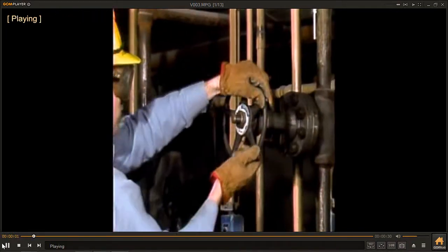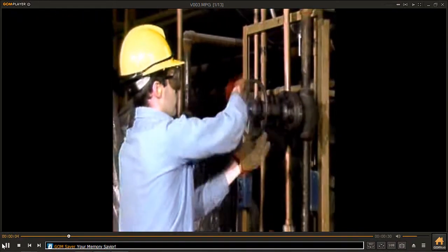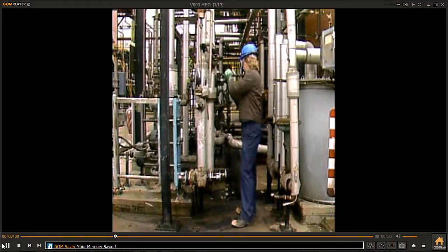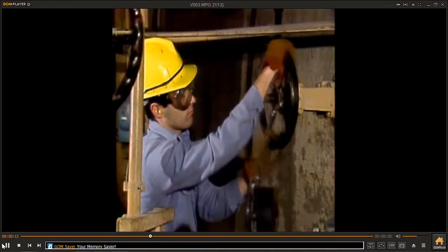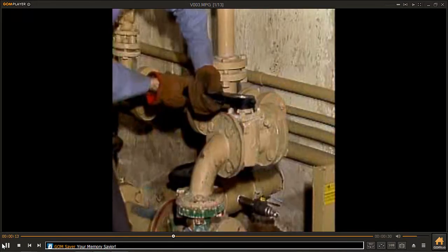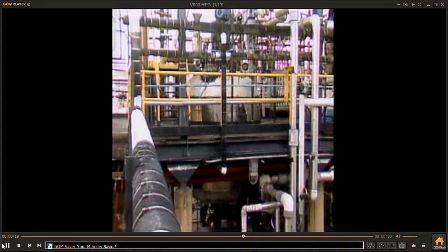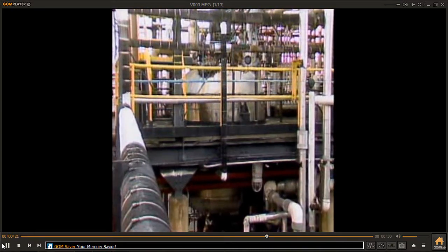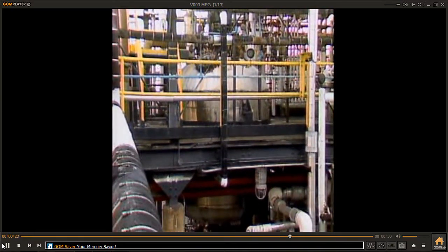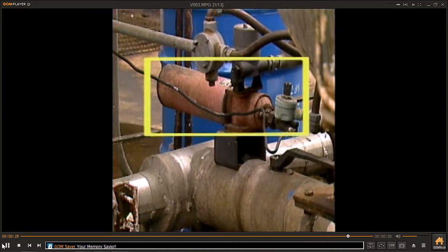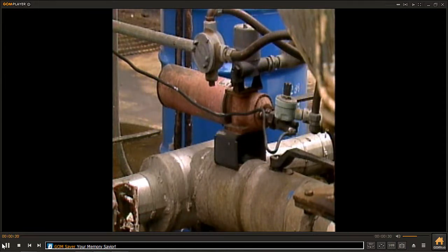Valves are used to control the flow of fluids in process systems. In order to meet the needs of a process system, some method of changing the positions of valves is needed. Some valves can be operated with hand wheels or levers, but some valves have to be opened, closed, or throttled frequently. Manually positioning valves in these types of situations is not always practical, so instead of hand wheels or levers, actuators are used to position the valves.